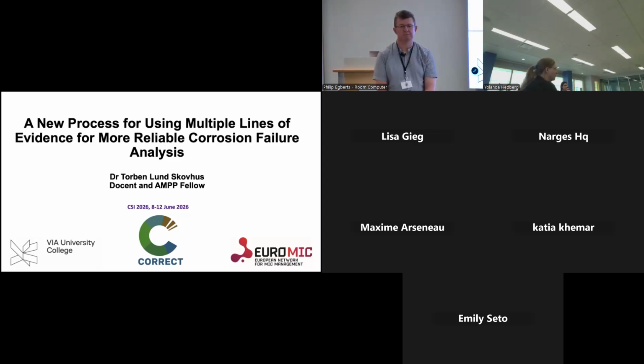In the cold leg, they just had a massive deposition of corrosion product containing a lot of iron and other spinel-like structure. But in the hot leg, it also showed a massive amount of dealloying and dissolution, up to a few hundreds of microns. So if it hadn't failed and blown up there, it would have probably broken through the wall in the hot leg. But a big thing in the process is to always try to do everything you can before you start cutting and sectioning, because you can't go back.